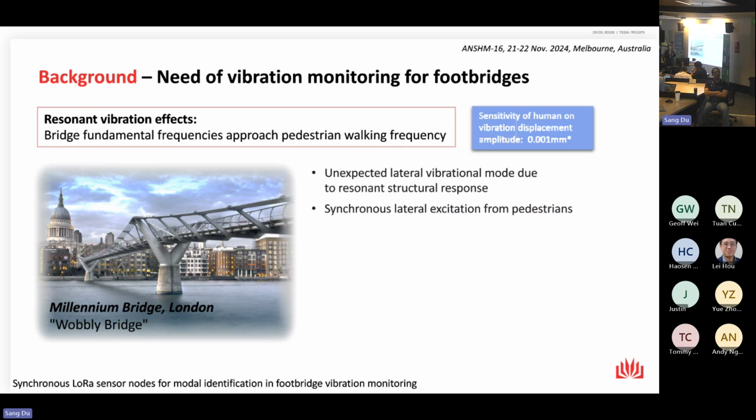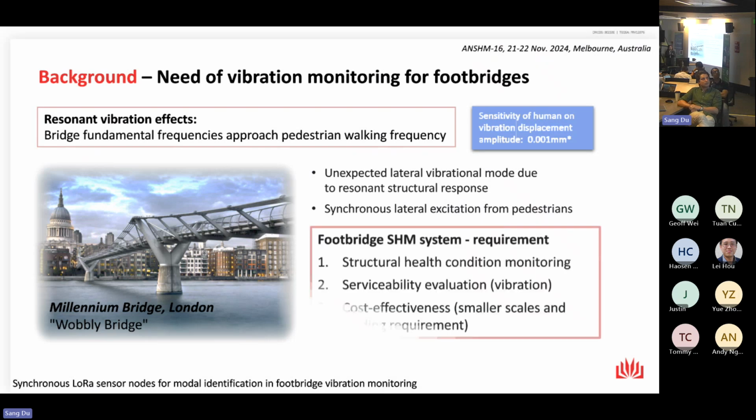The large vibration of the footbridge may not imply any structural damage immediately, but it still makes the structure suspicious and may lead to some deterioration over a long time. Therefore, I think a monitoring system for footbridges should contain not only the function of health condition monitoring, but also serviceability evaluation, which is exactly to monitor the vibration of the footbridge.